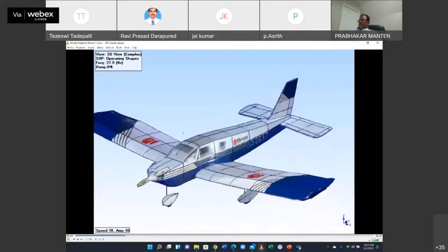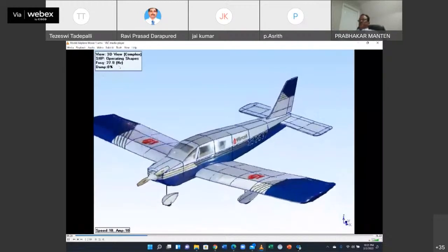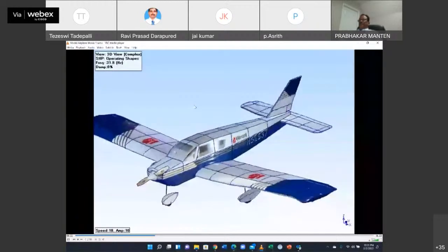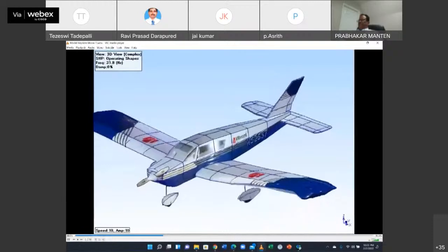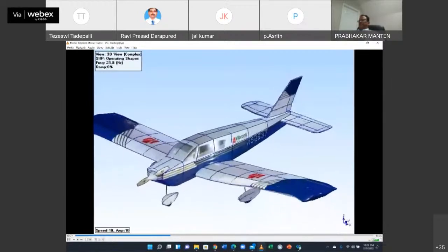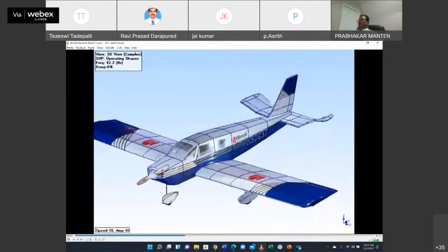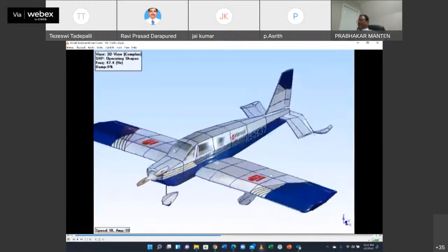The company which makes all this equipment conducts this on a model airplane, a complete modal analysis, and shows you different hertz. This is a frequency of 27.9, then 33.8 hertz. You see something or the other is changing, right? All particular modes they captured. At the back tail end, that frequency coincides with the forcing frequency. At that, the second mode of that tail and some movements here.